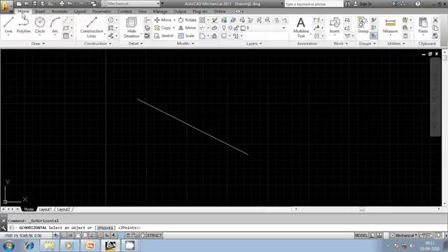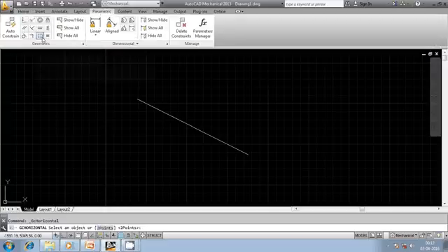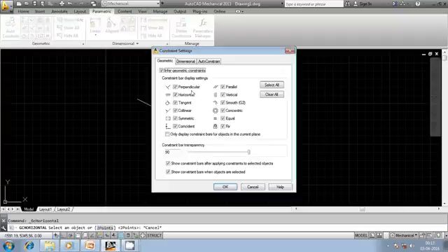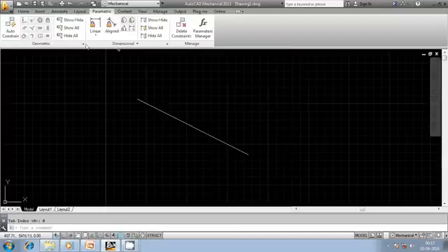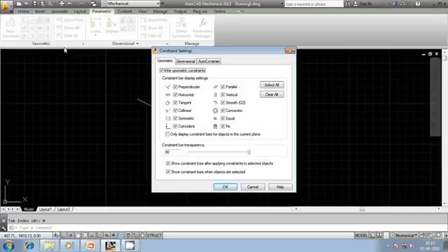In AutoCAD, let us see how exactly we can make use of these things. You have to go to Home, then Parametric. In Parametric you can see 12 symbols here. Then in order to invoke the constraint settings, you have to left click on the arrow mark in this area. You're going to get a pop-up window like this. Initially you're going to get Geometric. In this you're going to get 12 different symbols. Whichever is applicable you can select, whichever is not applicable you can switch off as per your requirement. If you select infer geometrical constraint, automatically the geometrical constraint would be applied to the geometrical entity.